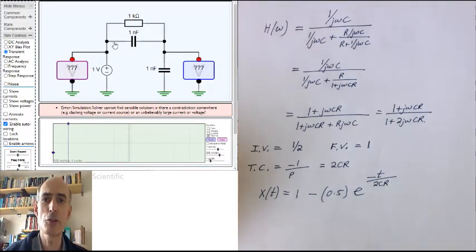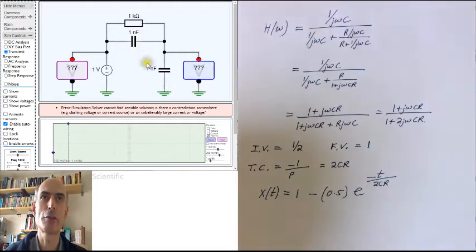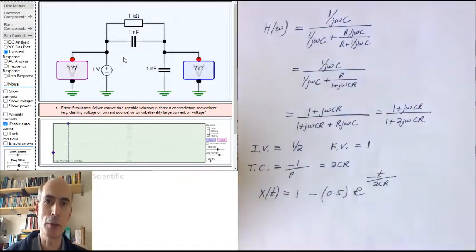The initial current would never be infinite, because in real life wires don't have a zero resistance, and there would be no such thing as a voltage source which didn't have some finite value of Thevenin equivalent resistance in its output. So the current wouldn't be infinite. It would be very large when you first switched on the circuit, but not infinite. So the maths wouldn't actually blow up like the transient simulator thinks it will.